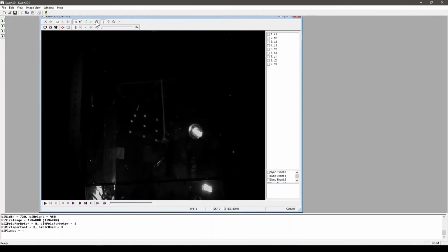Now if I click the calibration frame, we can see how our calibration frame is looking, right? We have 18 points, so I will untick, and our wing is inside the wind tunnel, the calibration frame. The next thing we have to do is digitizing mode again. As we can see, we have 114 frames. We can take each frame and select 9 points. After I click digitizing mode, we see 9 points, right?